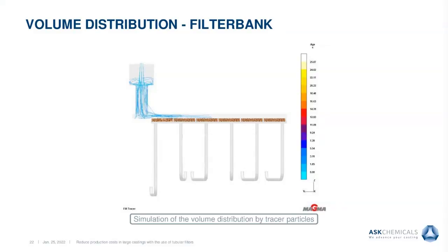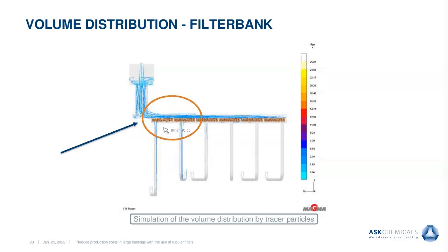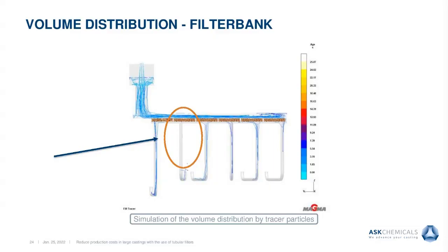When we start with the normal casting process, the runner is filled more and more, and then the first melt is running through the runners to the ingates, and we see that the system starts with a different distribution of the metal. This is reinforced by the lack of filter support at the joints of the filters. Also, when inserting the filters in sequence, filter bits or ceramic inclusions can break off from the surface during contact and subsequently pass into the mold.